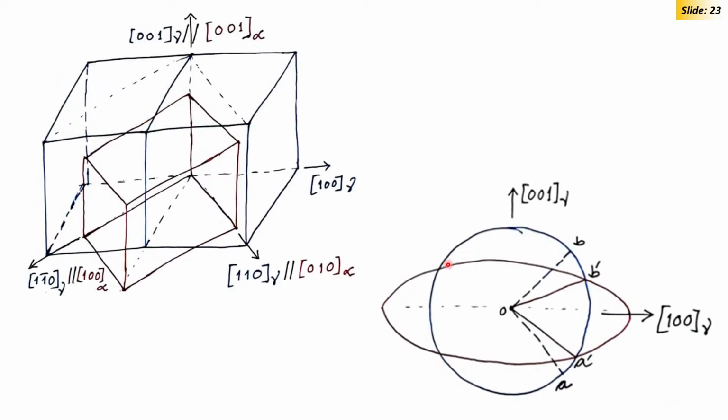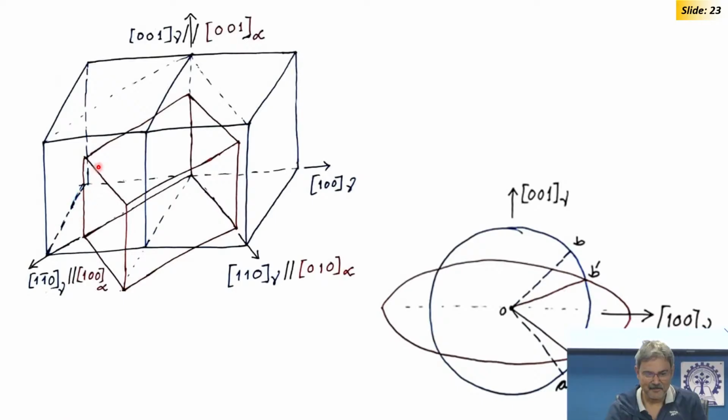So, in doing this, if I ask you which line remains invariant in the left hand side schematic, what is the answer? Is any line remaining invariant? Vertical line shortened, right? Other lines extended. So, none of the lines are invariant. Okay. So, in Bain model you cannot maintain an invariant line strain. So, it is a kind of approximation, but it is not correct. So, we are moving into more accurate forms.